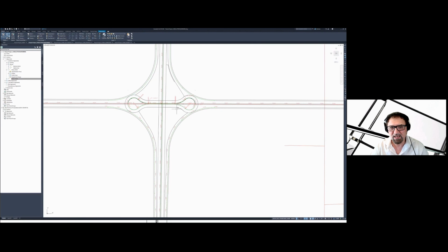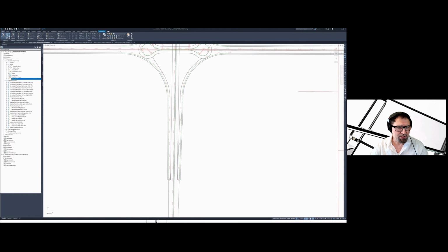If you look carefully at some of the shaping of the design here, because we have the turn in to this off ramp, there's more space left for that. Where we are on the off ramp, we don't require and don't have that much, so there is no such space left. So this is the difference between the off ramp and the on ramp. There are also a bunch of offset alignments for each one of these that you can see. And there are also curb return alignments. There are basically 4 of them. E1, which is, like I said, in the lower left corner.